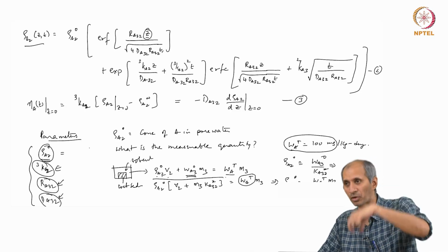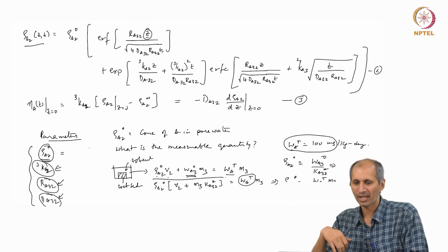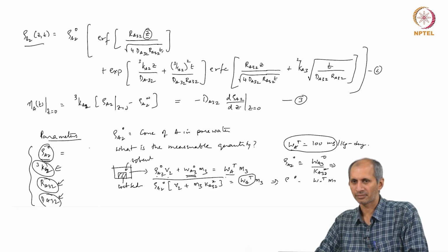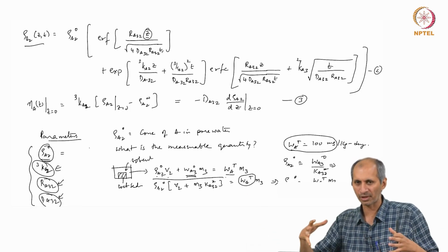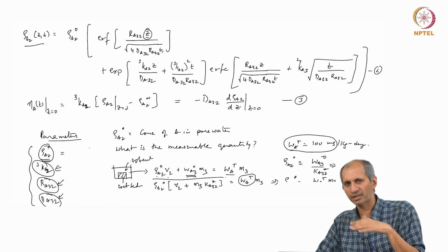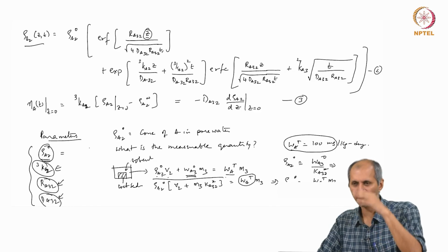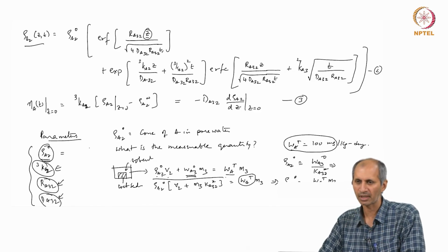That is the reason for having a core, because bulk density will change the moment you take a grab sample. You put it on this thing, it is all open now, and you are not retaining the original structure of it. But you can measure the in situ bulk density by grabbing a core and then carefully measuring the amount of water and the volume corresponding to that mass. You can do all those calculations based on that.